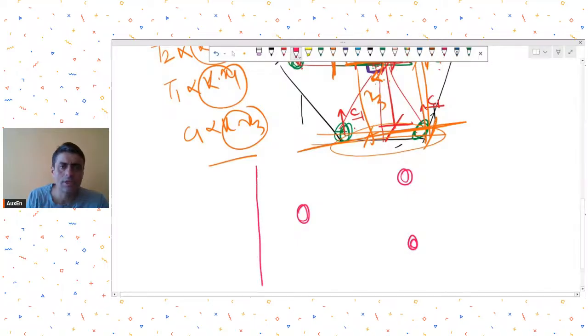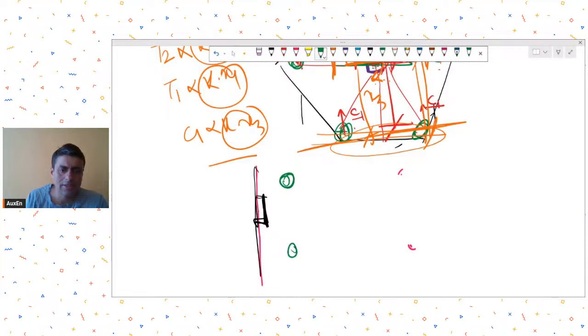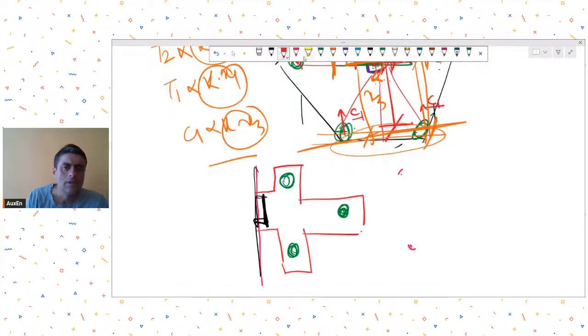generally, let's say this is my property line, okay, in plan view, and I have provided a column over here, and then I go for an eccentric pile arrangement, let's say like this, right? So my pile cap arrangement is like this. This is the plan view. So this is the column having some axial load. Now this distance you know, and this distance you know. So now you can solve using basic mechanics.